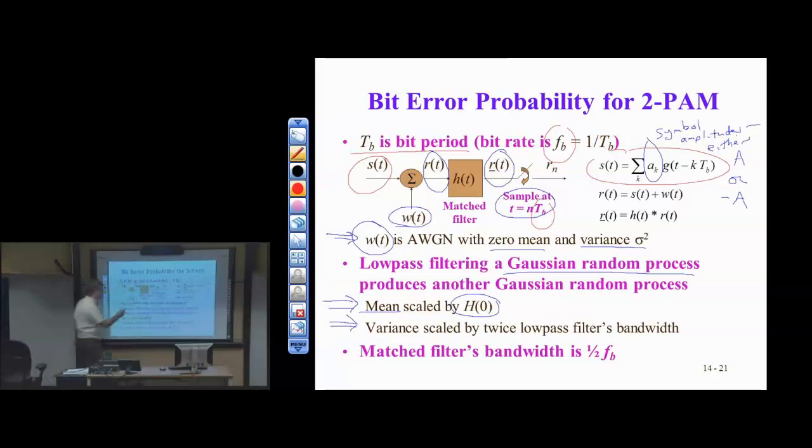Well, the stop band here, so this matched filter, you can talk about cutoff frequencies, which I do in the last bullet. So the matched filter is the anti-aliasing filter. The matched filter maximizes SNR. That's sampling output. And it's the anti-aliasing filter.